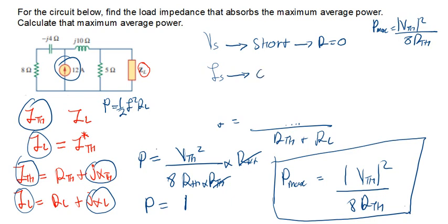If you switch off a current source, what you're going to have is an open circuit, of which resistance is going to be equal to infinity. It's just way too big, so there's no need of putting anything here. It's just going to be nothing. This part is going to be eliminated. That's when you switch off a current source, and that part is very, very important. We always have to remember: voltage source, short circuit; current source, open circuit.